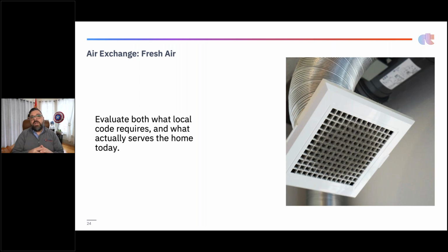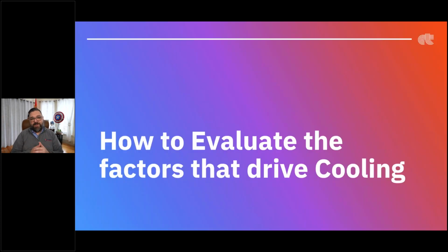And obviously, in our climates, we share similar climates. We want to make sure we condition that, right? So we either want to run that through an HRV or an ERV if we can have balanced ventilation. That's a good thing. We don't want to rely on just all the air coming through the unsealed penetrations of a house like where I live right now. It's not quite as comfortable.